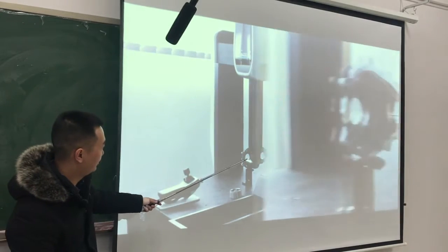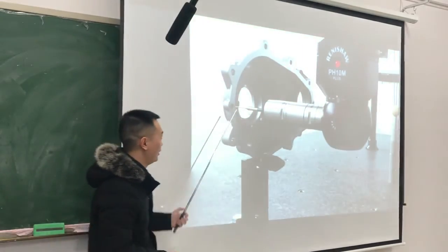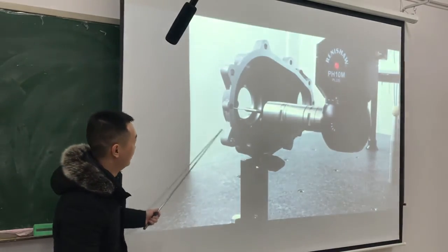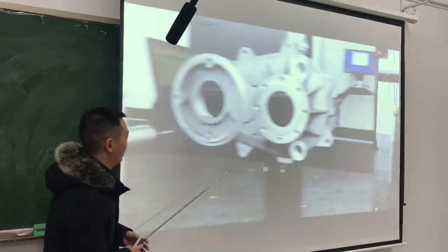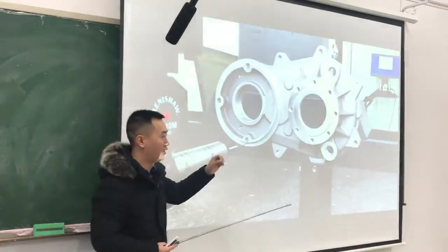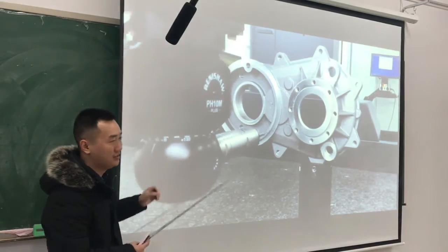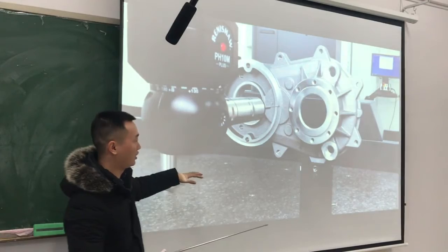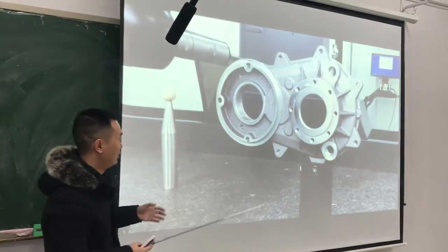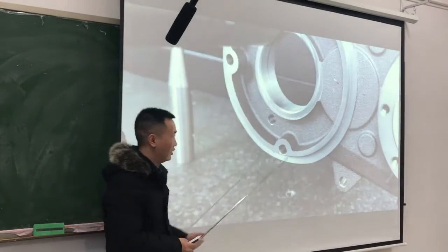As we can see here, this is the workpiece we want to measure. It has very complicated geometrical features, and here it just uses the probe to touch it. When it touches, it records the data. It's 3D XYZ data in the computer, and it will measure many points to generate a profile of the workpiece.